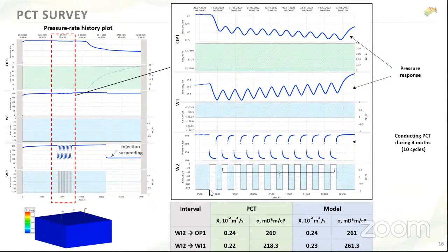If we open and shut the injector, our production deferment is very minor, maybe zero, maybe very small. But if we choke up and down our producer, we would have a production deferment in the generator well. So that's why, if the producing company has an injector in the area of interest, it would be more economical to use the injector as the generator well, because that would result in absence of production deferment.